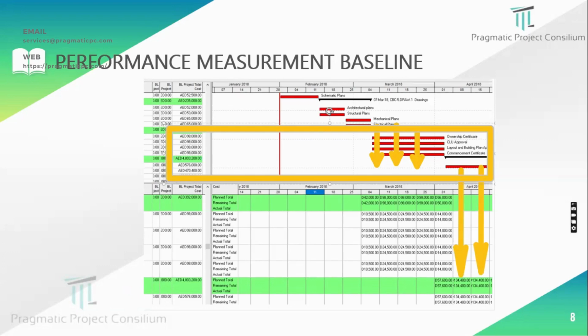There is some groundwork we have to take care of, and the output of the groundwork and the cost need to be distributed to the activity level. That is what we have done here. So all of this is included with the manpower, material, and cost. Man hours, of course, material, what type of material we are going to use for this, and other costs such as equipment, and what equipment we are going to use. Accordingly, we have to calculate and distribute it as a cost.